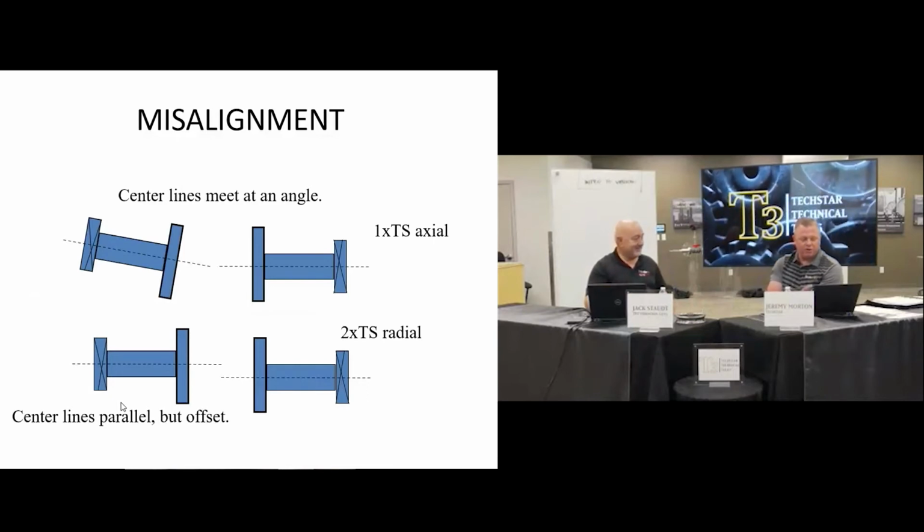I guess what percentage of the work you do is alignment work right now, Jack? Are you doing a lot of alignments or verification of alignments primarily? Yeah, a lot of times they'll call us to come in and verify alignment on machines out in the field. We come in using laser alignment tools, lock the machine out, follow safety protocols, and check the alignment.